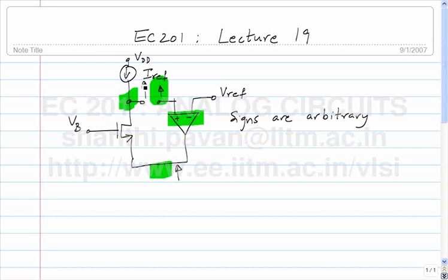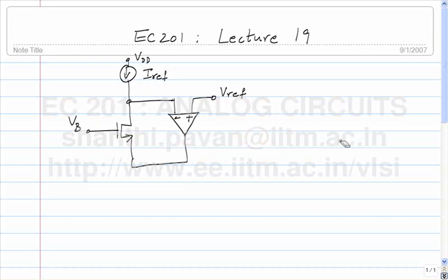So what is the conclusion? The conclusion is, with this particular choice of signs of the op amp, the feedback loop is actually a positive feedback loop, and therefore to make this a negative feedback loop, what we ought to do is to flip the signs of the op amp. So we derived the circuit yesterday, and today we saw that if the circuit was presented to you, you should also be able to put the signs on the op amp.